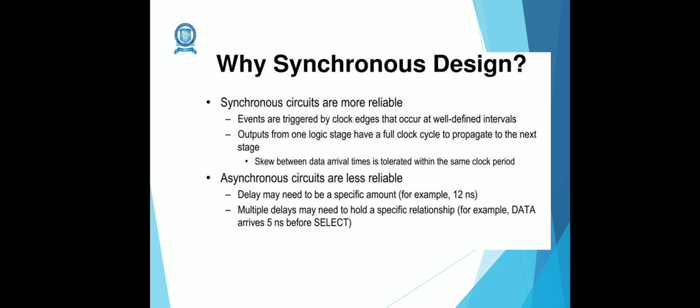An external clock signal triggers the IC to go from a well defined and stable state to the next one. On the active edge of the clock, all the inputs, outputs and internal nodes are stable in either the high or low state. Between two consecutive edges of the clock, the signals and nodes are allowed to change and may take any intermediate state. This behavior is predictable and will not fail due to the hazards or glitches introduced by the irregularities of the real circuit. So synchronous circuits are more reliable.